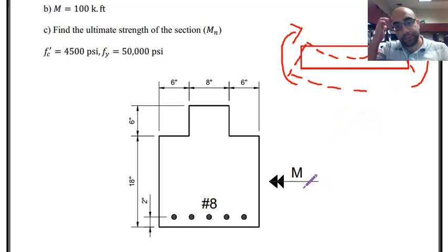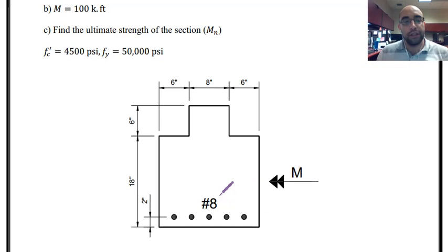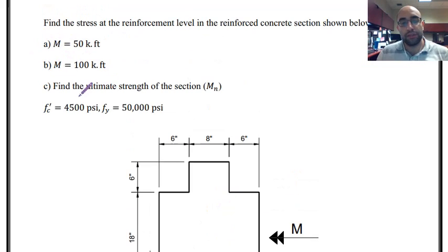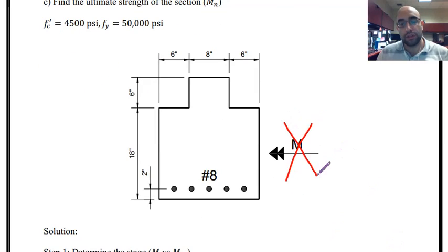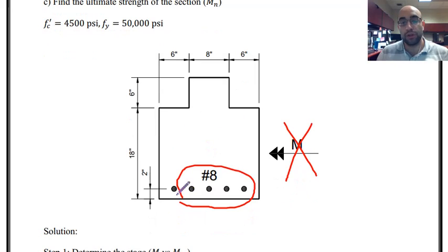Without this knowledge, if I just wanted to look at the section alone, and if, for example, these bending moments were given to us without having such a thing in the example, by default, we know that for such a section, bottom of the section will be in tension, top of the section will be in compression, because reinforcement is over here, and we know in concrete sections, we always put the reinforcement in the tensile region.